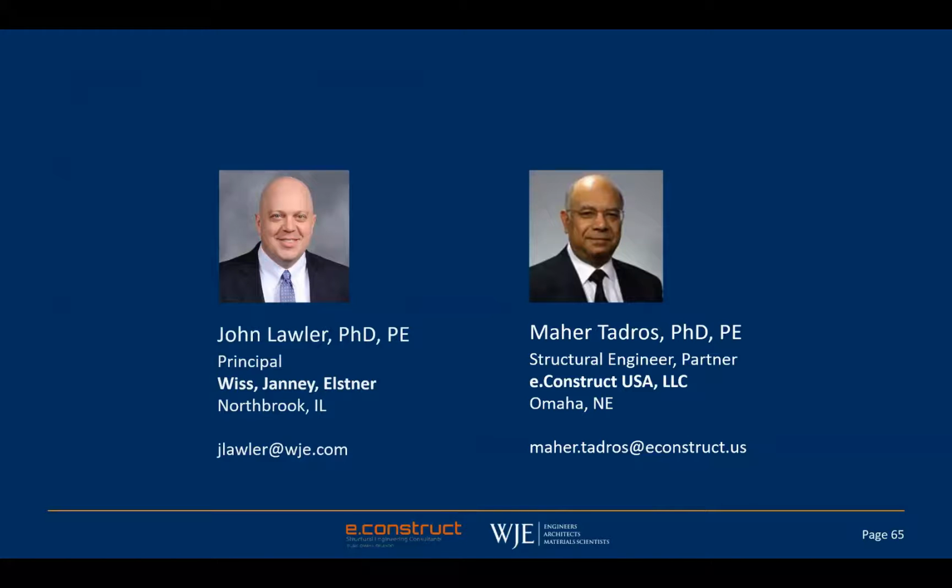And then what I'm seeing is that when we start comparing UHPC to other corrosion resistant materials like stainless and carbon fiber, UHPC is very competitive and introduces so many more additional benefits by having a more efficient structure, and the concrete durability is so much greater. So when you're in a corrosive environment and you want to use stainless, having a durable mix like UHPC is a significant benefit.